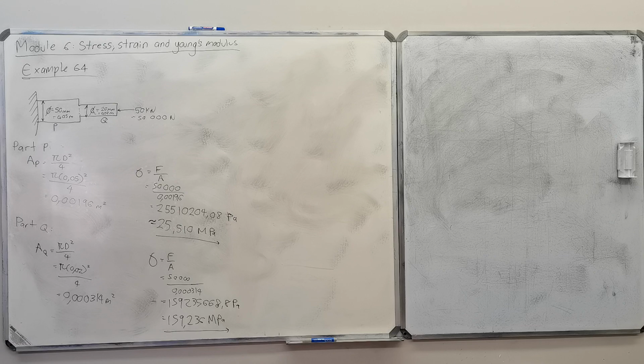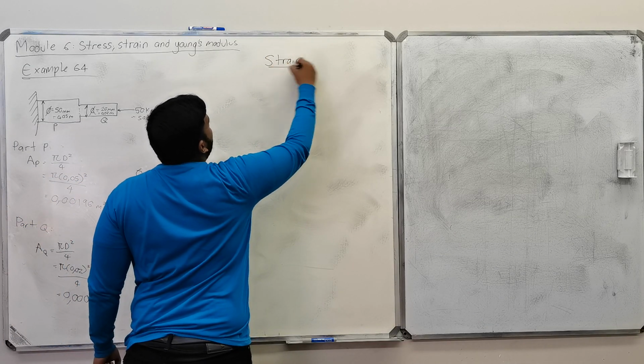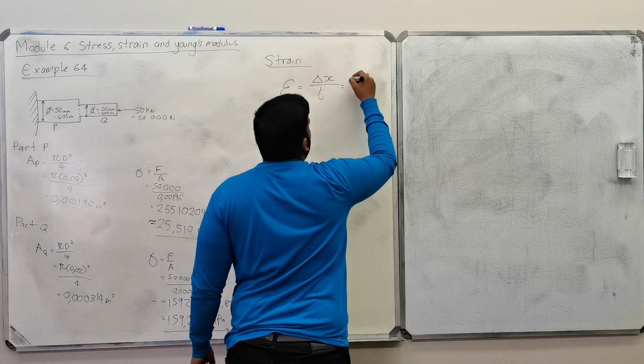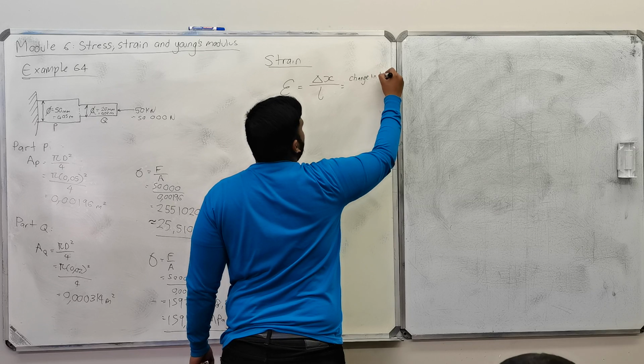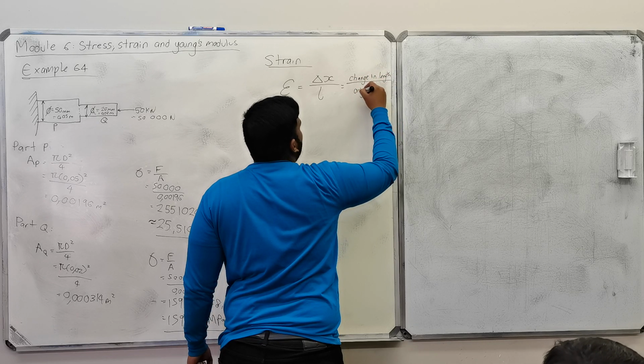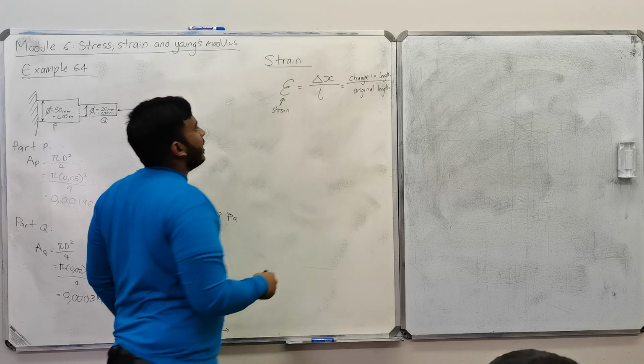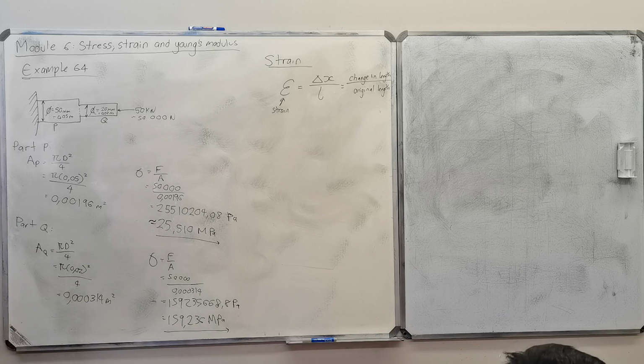Yeah. Then we get this formula for strain. Strain is defined as the change in length per unit length. You can highlight that as the definition. So strain is equal to the change in length all over the original length. There are no units for it because you end up with the same unit divided by the same unit, so it's a dimensionless quantity. Okay, straightforward. Let's do an example.